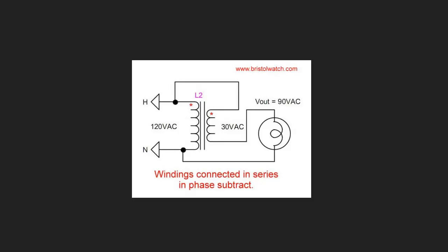Now, how does it do that? How does it cancel some of the voltage? This is one of the tricky parts that's elusive, shall we say. Basically, it cancels part of the voltage because you could say that the inductance is reduced, or you could even say that the magnetic field is restricted by bucking at least part of the total input field. And you've got to remember that it's the time rate of change of the magnetic field, which is the same as the changing current in the coil, that creates a voltage.